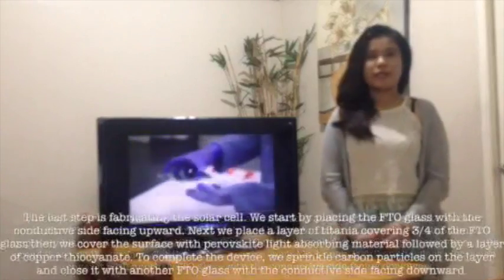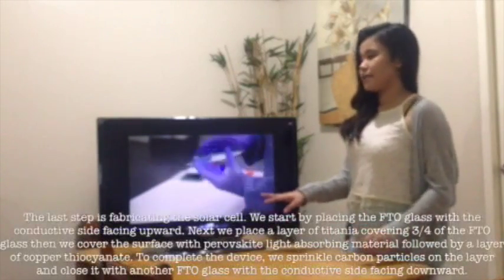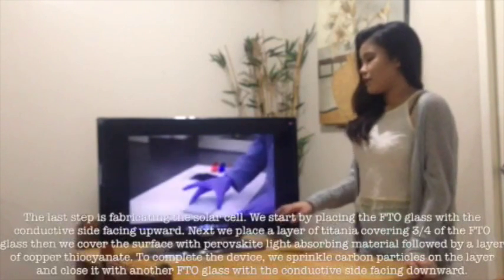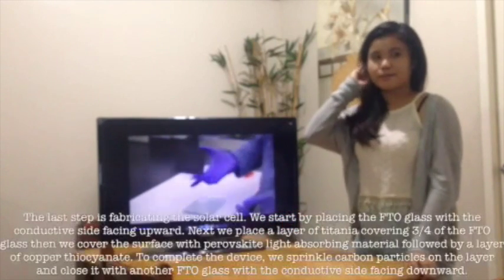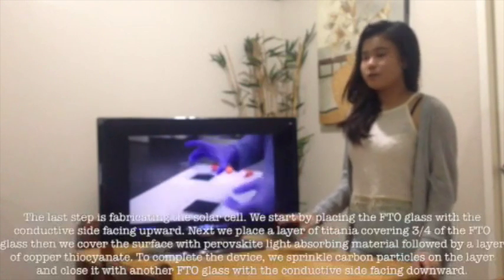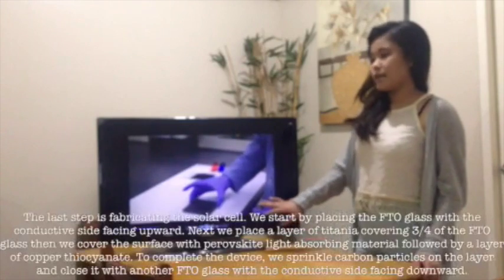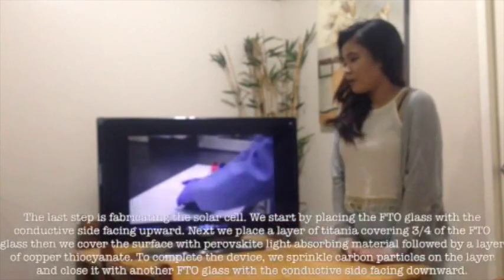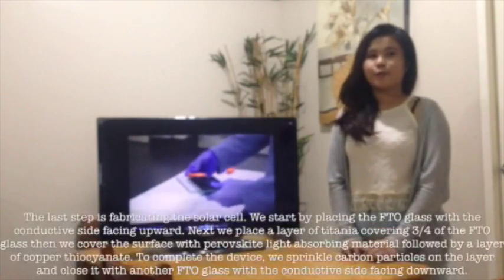The last step is fabricating the solar cell. Start by placing the FTO glass with the conductive side upward. Next, we place a layer of titanium solution covering 3/4 of the FTO glass. Then we cover the surface with a perovskite light-absorbing material. Next, followed by a layer of copper thiocyanate. To complete the device, we sprinkle carbon particles on the layer and close it with another FTO glass with the conductive side facing down.